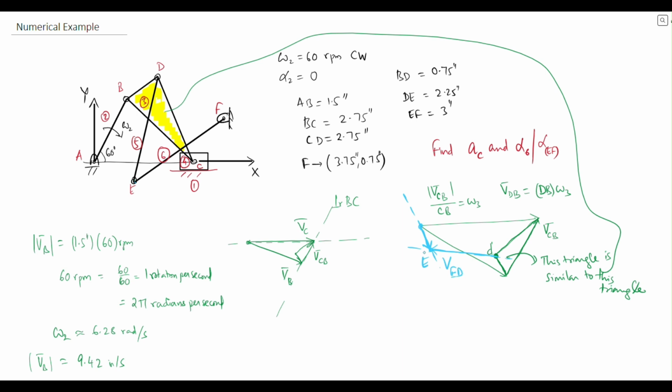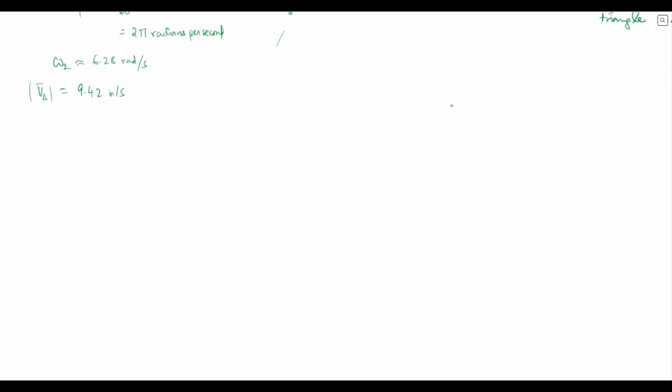and this is the velocity of E with respect to D. This is velocity of E. You can measure these off from the velocity diagram drawn to scale, and then obtain each of these velocities that we are looking for. Thereafter, we can identify various accelerations.